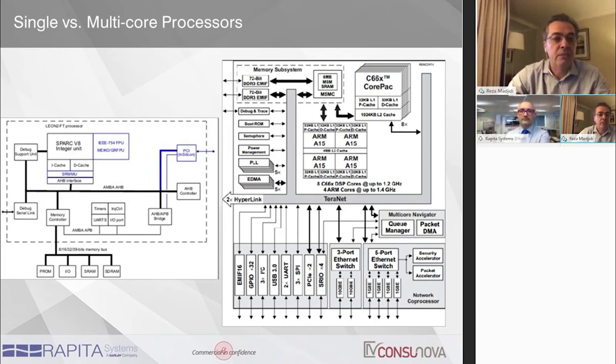You could have a symmetric multi-core processor with one RTOS managing the partitioning, robustness, timing, and resources, or you could have asymmetric partitioning with a real-time operating system loaded on each core, and how that RTOS governs the OFPs or application software is very different and unique for each case.